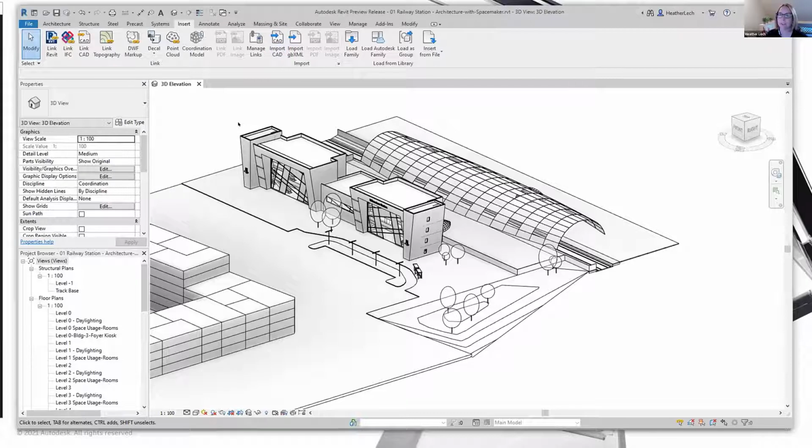So that would be the other workflow, like where Jason isolated a certain part of the model. You could save that piece off as a separate FormIt model, and you could directly go to Import CAD here, search for that FormIt model and bring it right in here. So those are two newer workflows in the latest version.